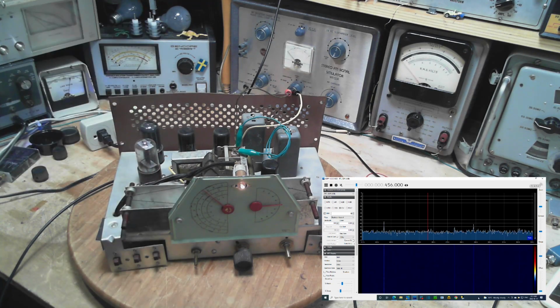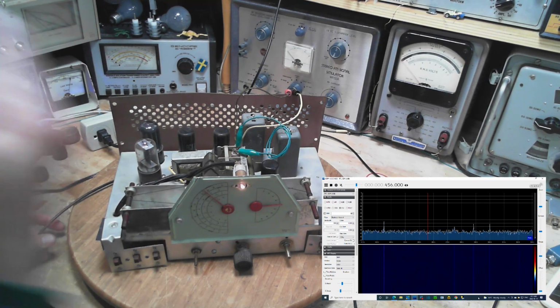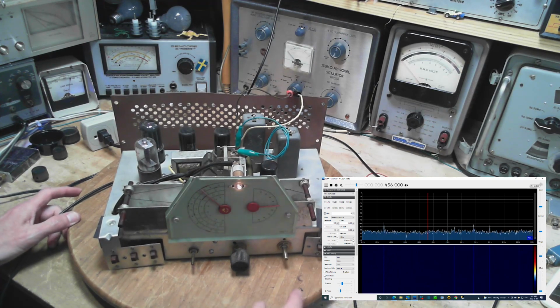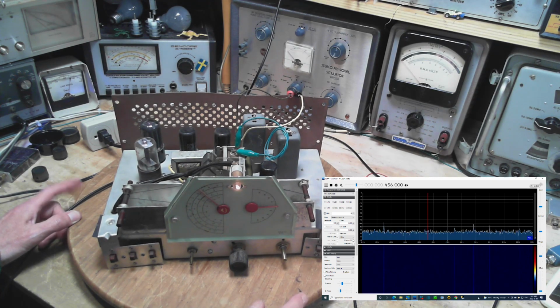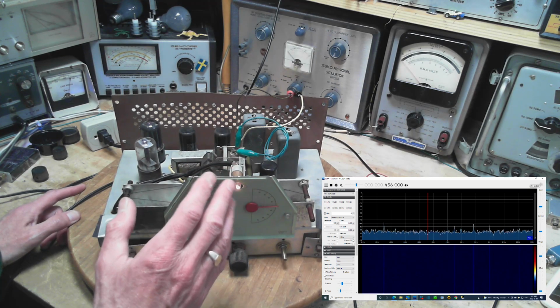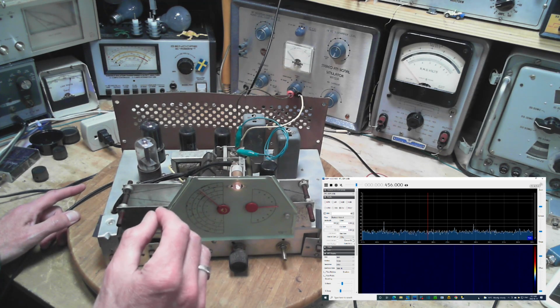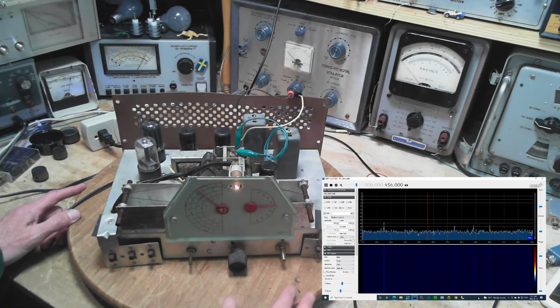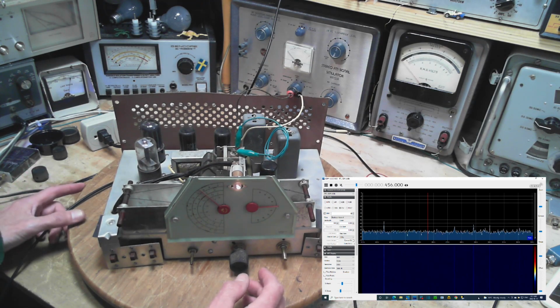And you know what? If this radio had another front end tube, an RF tube and an RF circuit, this problem might be much less, because the 455 noise signal would have to get past the front end tuning. There's more of it with the extra RF tube. So how much noise is this compared to the noise that the oscillator converts in, if I can put it that way? The radio's tuned to a certain frequency.